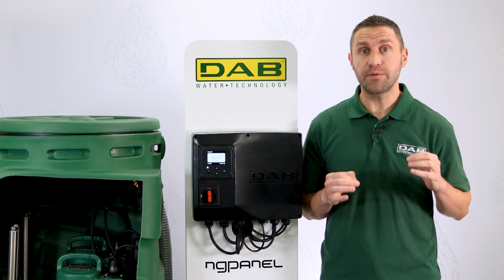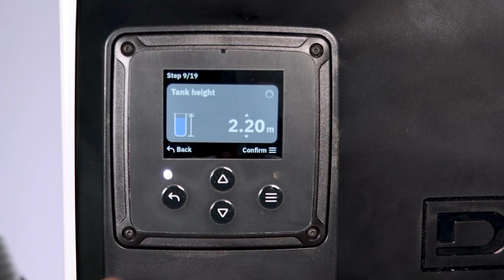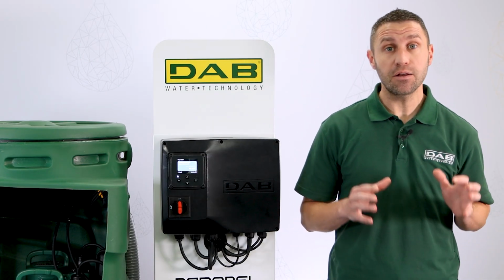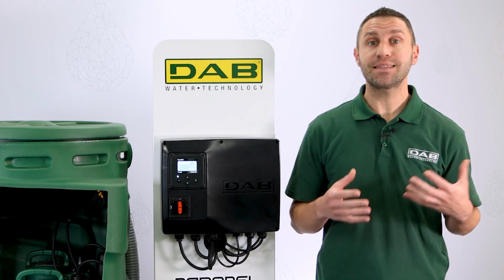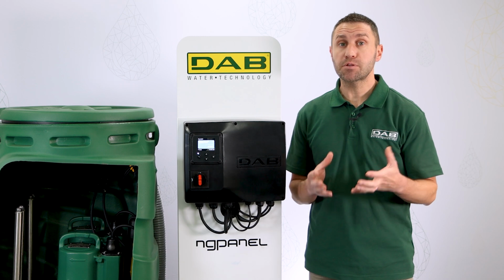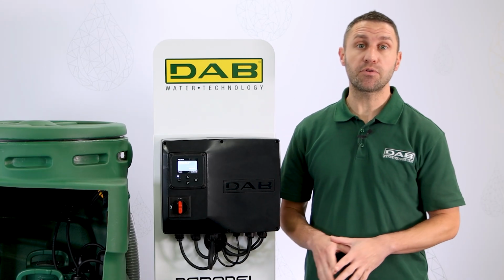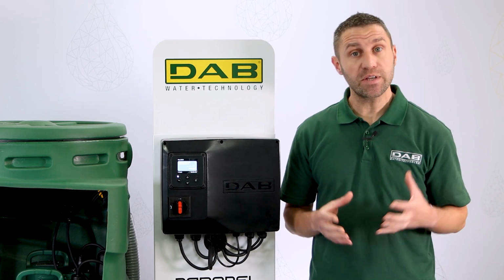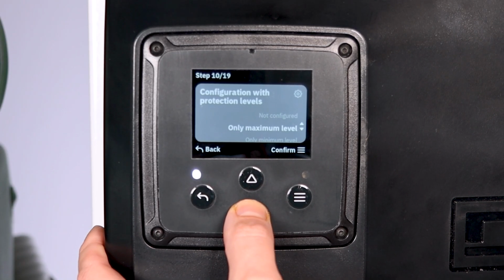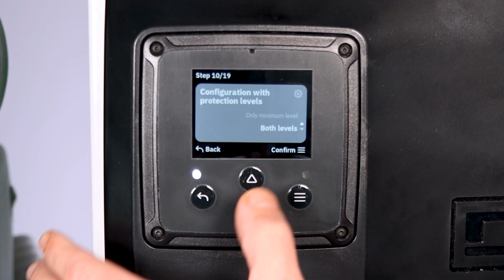Now, I choose the operational levels of the installation. The first input is the tank height. Here, we have to choose the high and low protection levels that are detected by my depth sensor. The high-level protection alarm helps to avoid the tank from overflowing, while the low-level protection alarm helps to avoid the pumps dry running. If protection level switches are not present, we recommend to select both levels.